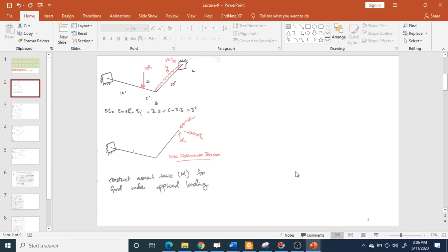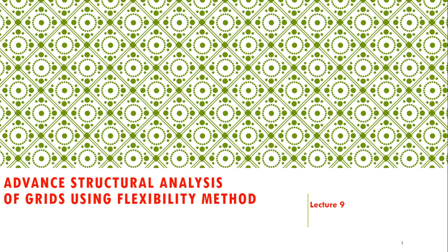Okay, today's new lecture is on analysis of grids. I've already explained what grids are. A grid is a structure whose members lie in the x and z axes, and there is no member in the y axis. However, the loading is essentially in the y axis.